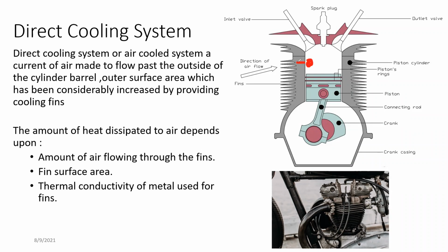Then it actually transfers those through the cylinder wall, right? So in this process, the heat transfer is conduction. The heat conducts through the cylinder wall and comes up to these fins, right? These fins then transfer the heat up to the atmospheric air. And with the atmospheric air, what actually happens is it uses convection.